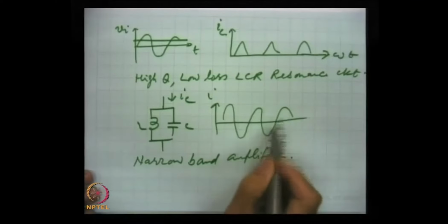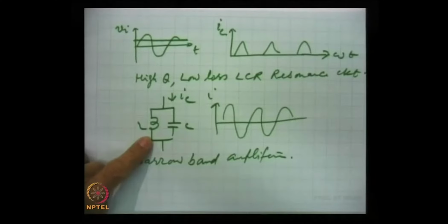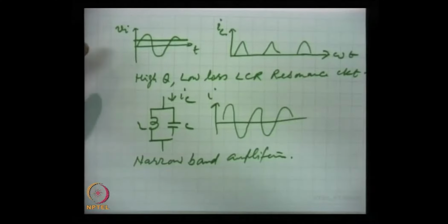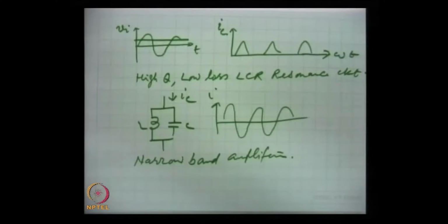For radio and television signals, high power carrier waves are to be generated, their efficiency will be a big consideration, and in class C amplifiers the LCR circuit is tuned to the carrier frequency, and from here the high power pulses will be transmitted.